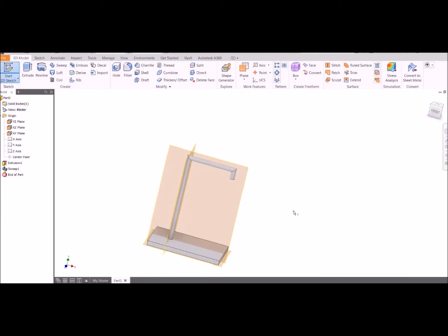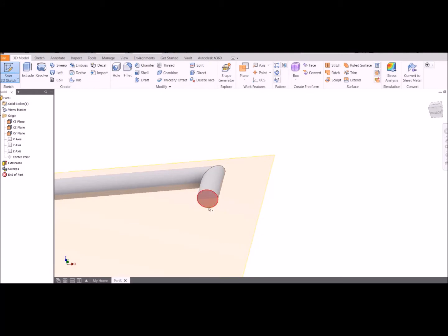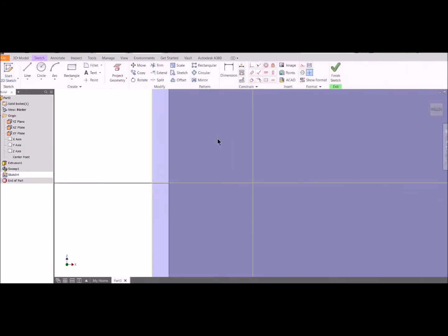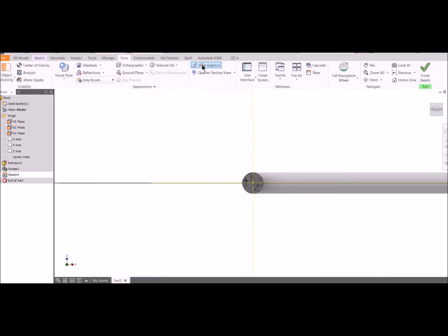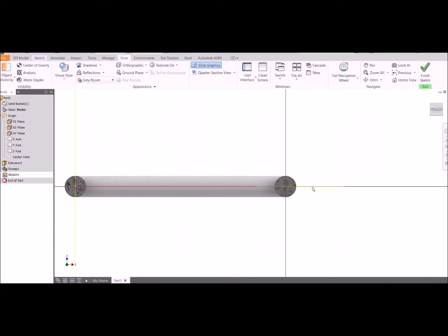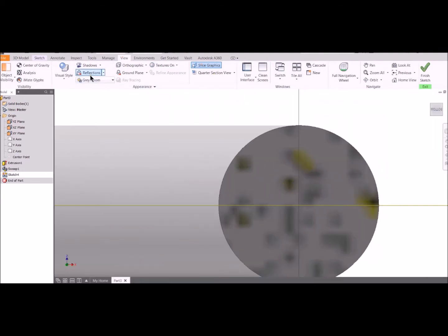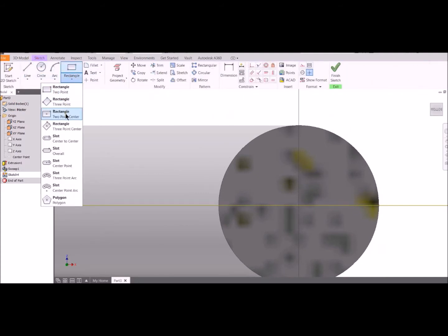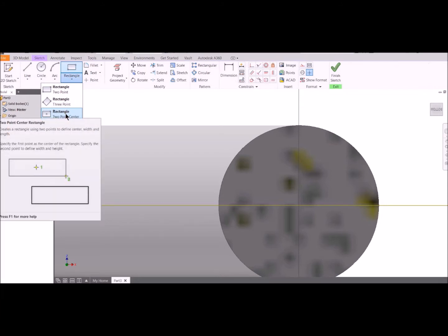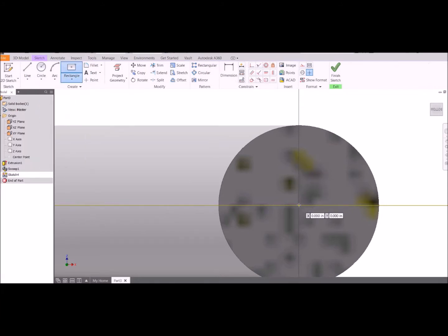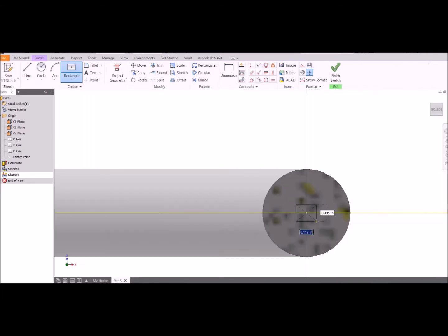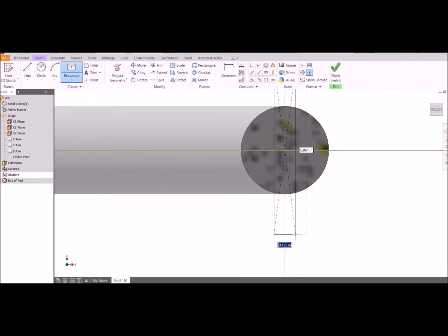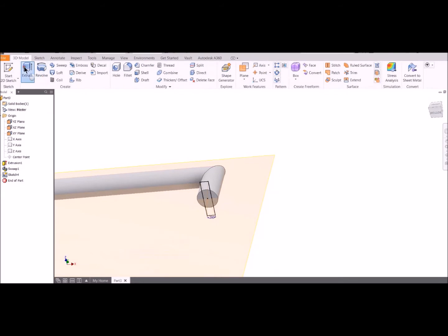Okay, now we need some way to attach our pendulum onto this frame. So I'm going to go ahead and slice a little connector into here. Remember, view, slice graphics. Make sure you're cutting into the right side of this thing. And I'm going to go ahead and grab the rectangle that you can make with the center point on it. So that'll allow us to just snap it to the center here really easily. Doesn't really matter how long it is. I'm going to make it 0.2 inches thick, and this is where our pendulum bar is going to kind of fit up inside of there.